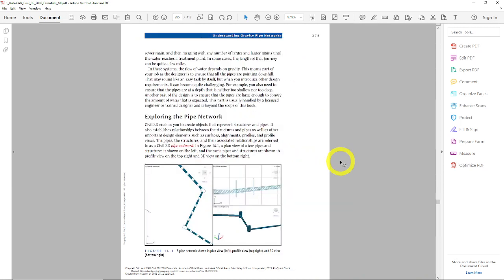Now pipes, there's a few more things to explore. It discusses more on pipe networks here in 275. There are 3 things really, additionally, to those main design tenets of pipe networks. They have to be not too deep, but not too shallow. So that sounds kind of weird. If they're too deep, like I've said before, they're cost prohibitive at times and difficult to build. If they're too shallow, they might freeze. They might have other things. They might conflict with other utilities. That's a very critical thing as well.